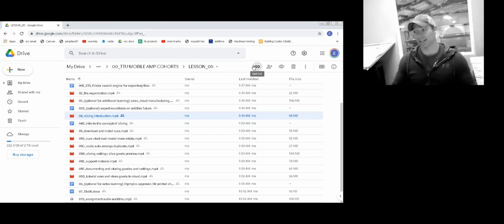Now, you can actually take a G code and load it back into your slicer, and the slicer basically gives you a version of it. So if you want to review a G code to see how well it will print before actually printing, you can take their G code, slap it into Cura, and then it's going to give you basically an executed version of that. And there are also G code readers that will show you what's happening in the process too. So it's a really good experience.